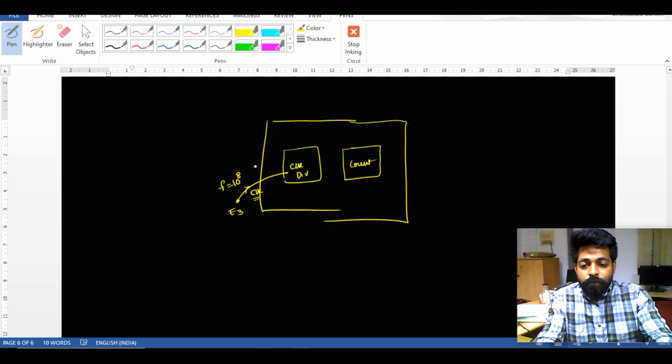Yes. So direct reset also will be taken from this one, and now it will be generating output, that we call a new clock. That new clock will be given as an input for the counter circuit along with the reset, so that the counter will be generating 4 outputs. This is the count of 0, this is a count of 1, this is a count of 2, this is a count of 3.